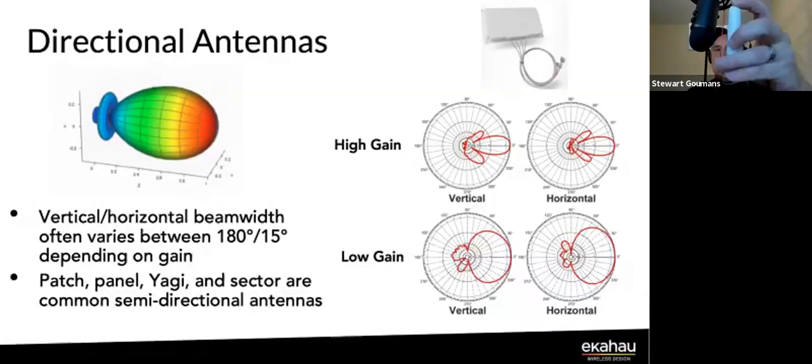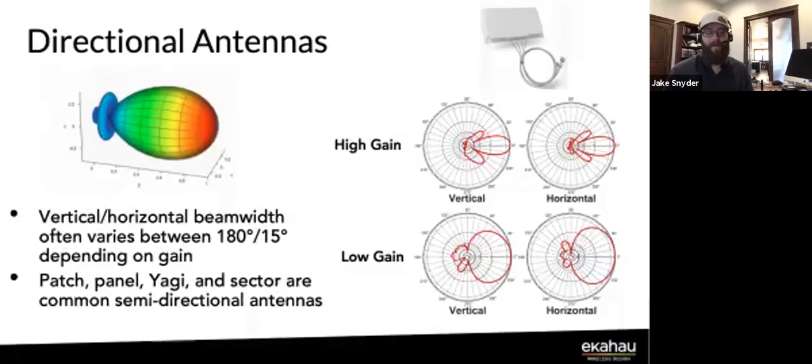It's a very small looking antenna, but that's the size of it right there. A traditional rubber duck, or dipole antenna, is more of that traditional donut shaped pattern. And a lot of times you don't necessarily want that donut shape, especially with the hole in the center,